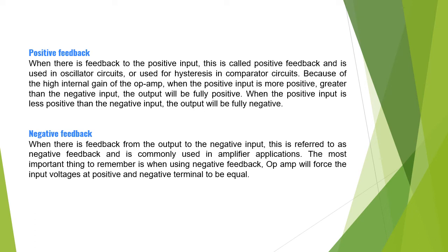Negative feedback. When there is feedback from the output to the negative input, this is referred to as negative feedback and is commonly used in amplifier applications. The most important thing to remember is that with negative feedback, the operational amplifier will force the input voltages at the positive and negative terminals to be equal.